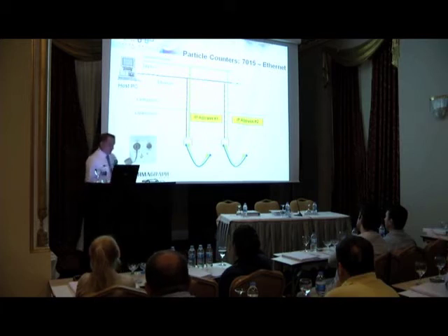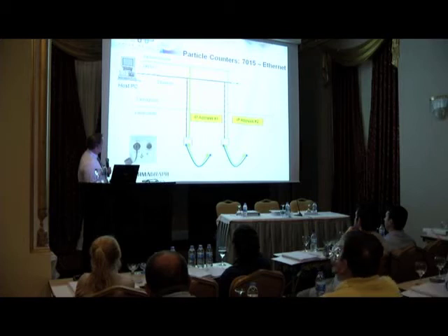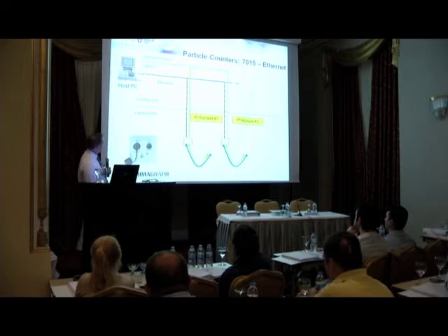We've got a couple of different architectures we use. As Matt talked about previously, you have your PC here, you have your vacuum tubing and your data cable. This will run from the plant. The PC will live in an office area generally, and then you'll have data running into a plant room area, and you'll have vacuum and data which will run down the wall of the plant room to this socket, and as we said previously, fed by the umbilical to a particle counter.